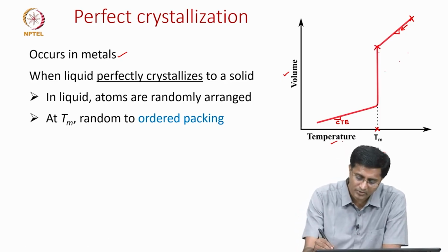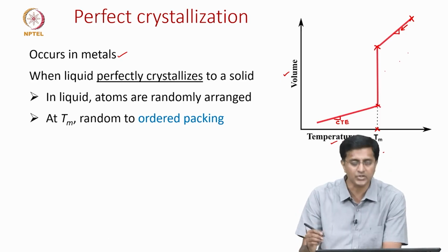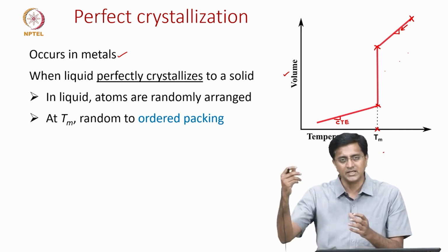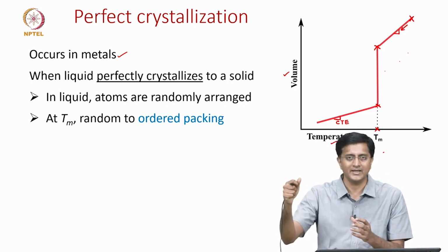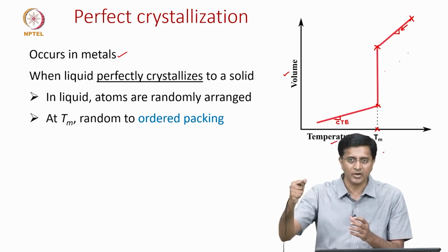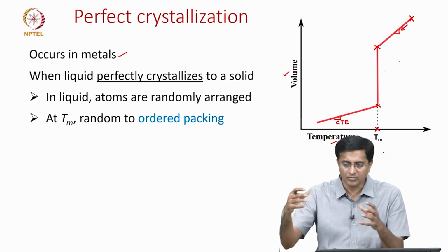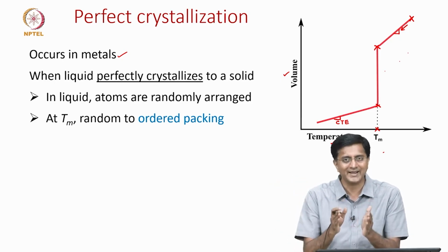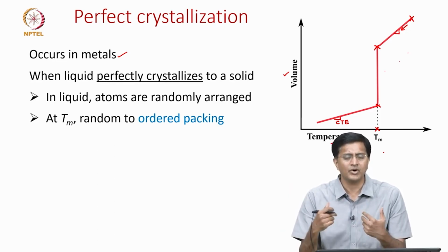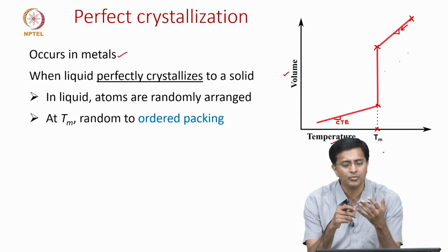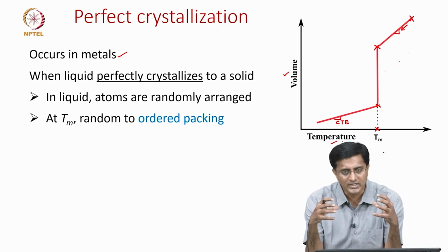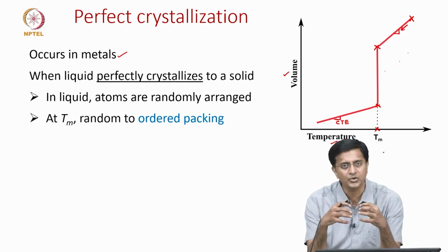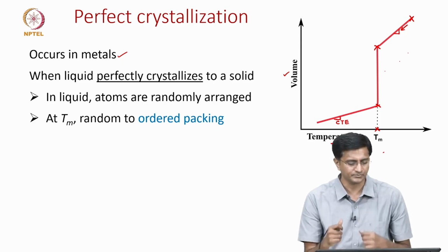From here to here is the crystallization process, where these atoms, which are currently very mobile and jiggling about their positions, come into a very close and tight packing. For metals you might have heard about body centered cubic lattice, FCC. These are the ways by which atoms come together, and once crystalline they stay in that structure.